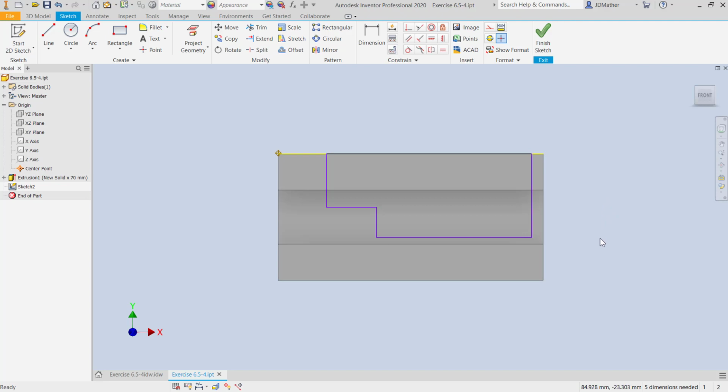And so one of the actually two important tips now that we've covered, two critical tips. Tip number one was draw one rectangle or one circle or one line and dimension it immediately for a sense of scale for the rest of the sketch. The second tip is when things don't connect together like you would expect they should, drag points around and look at the behavior. Do the lines stay horizontal? Do they stay vertical? I see that I want a coincident between this point, and that turns black.